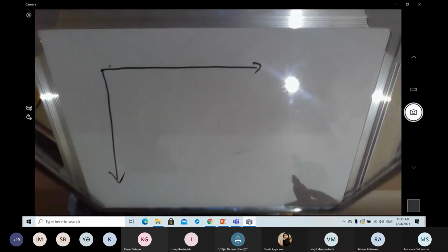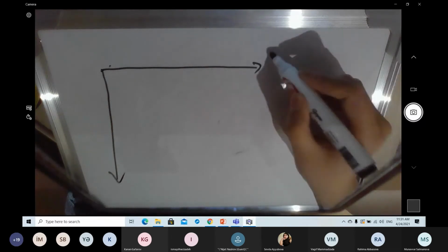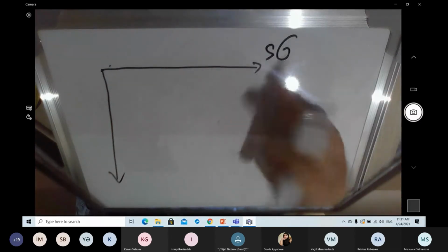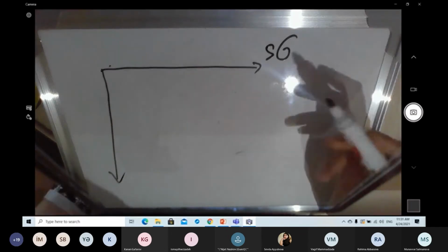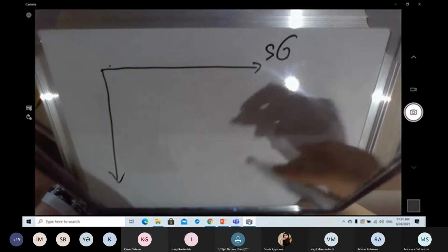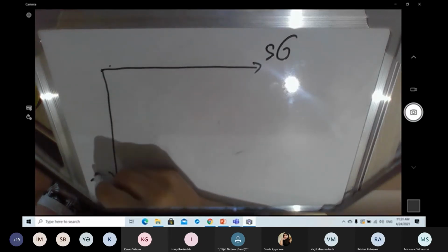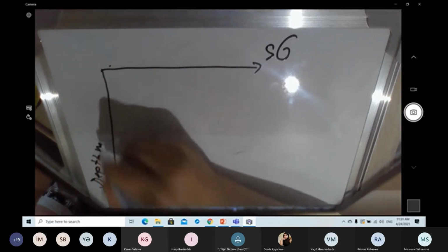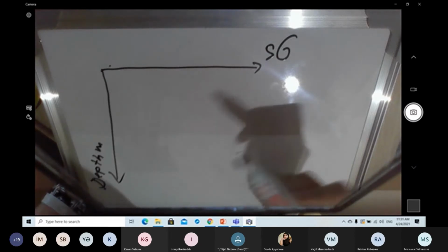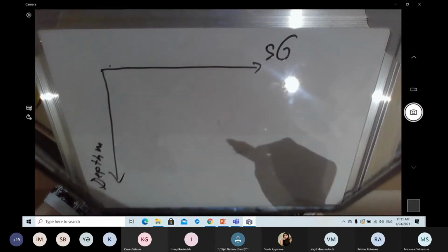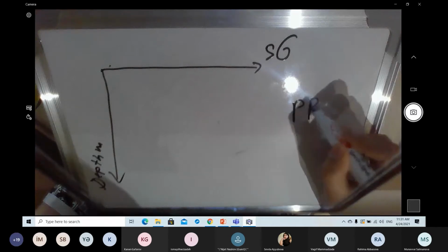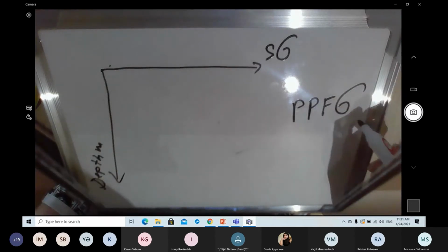So I just wanted to explain pore pressure and frac pressure and how we decide casing depths. Let's call it in SG, so it can be the density of the mud, and it can be our frac gradient, pore gradient. I will have a graph here showing that, okay? And this will be depth in meters. So probably you have seen this window, we call it the PPFG window, pore pressure and frac gradient window.